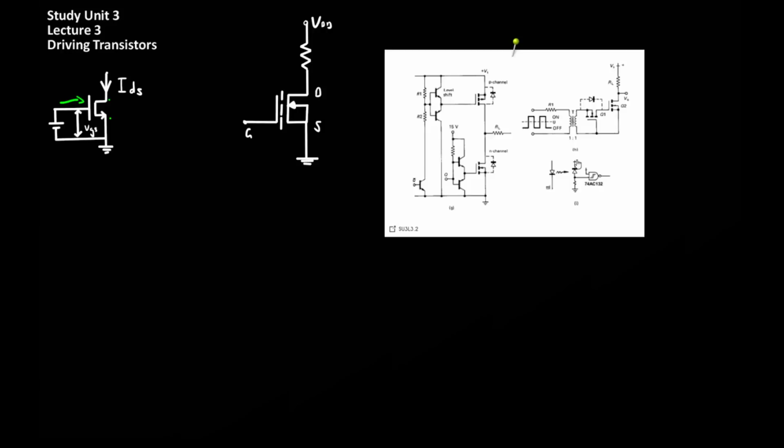All these different switching circuits can be categorized as either high side or low side circuits. Low side circuits are where the switching circuit is at more or less the same potential as the output driver or the supply rail of the power MOSFET being driven, whereas high side circuits are circuits where some other level shifting is required between the switching circuitry and the actual power switch.